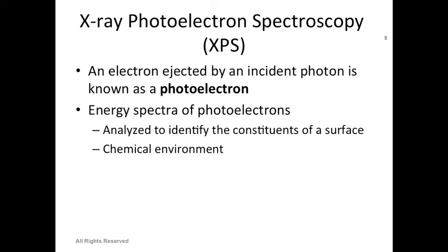We use X-rays to expose the surface of a material. Like we take X-ray and shine it on some surface, because X-ray is also energetic. They can also kick out the electrons. And when they kick out the electrons, those electrons are called photoelectrons, because you are using a photon source to kick them out, right? So previously when we were using an electron gun to kick out electrons, what were the electrons which were kicked out called? Secondary electrons, right? In this case, it will be called photoelectrons.